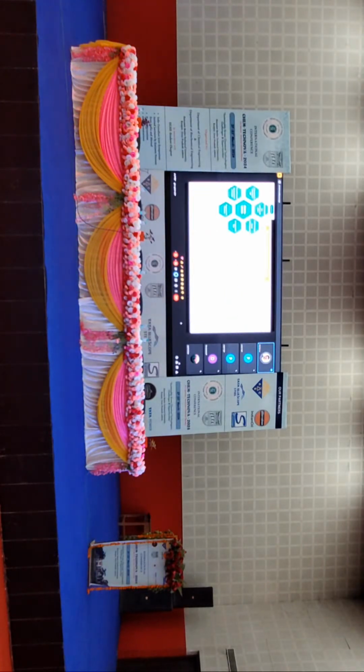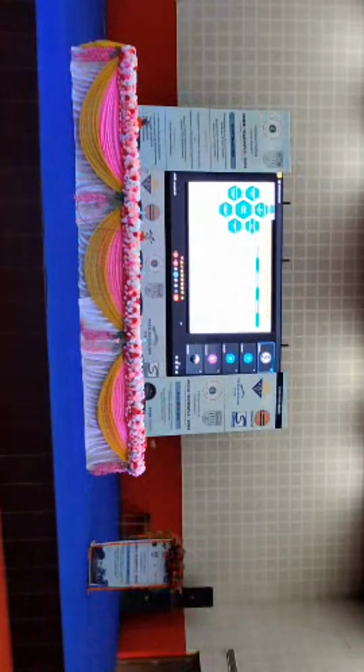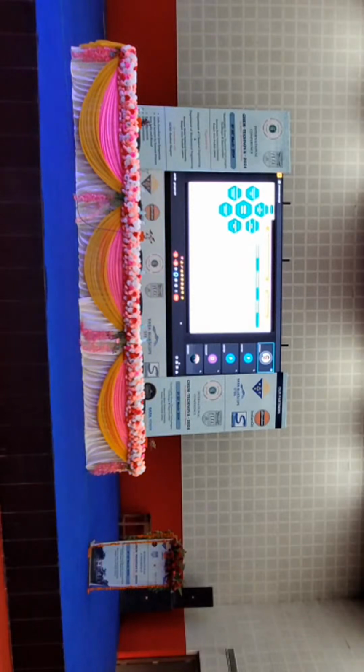What are the issues? In a traditional car, you may take typically 2 minutes. In 2 minutes, your full tank will be full, right? So if you want a similar charging time in an electric car, how much power do you need? It is a very simple calculation. Energy in 2 minutes, so 2 by 60 hour, right? So the hour will be cancelled. You will see you will need 1.5 megawatt of power.